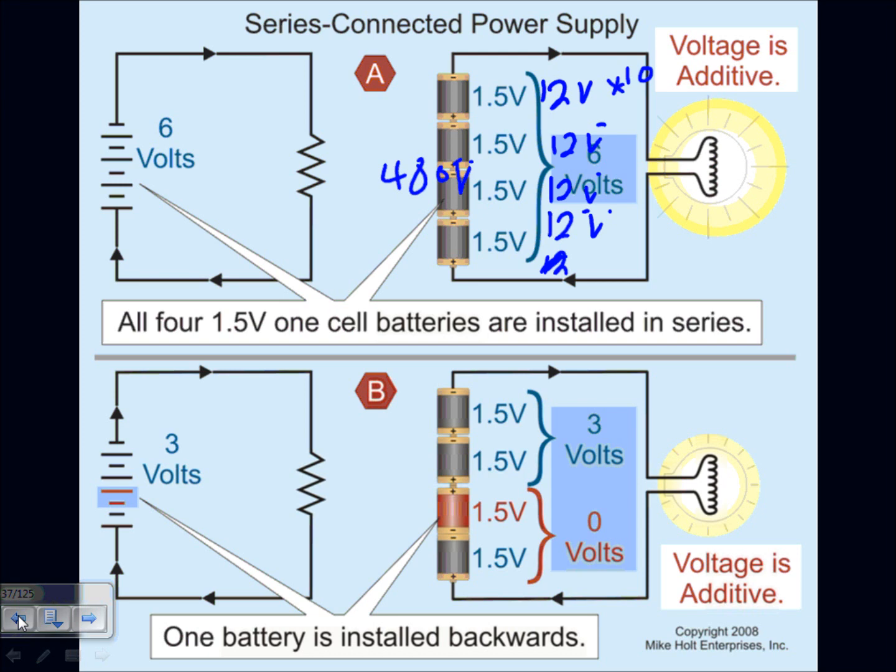Now, this string will give you 10 amps. Okay, so I got only 10 amps. I'm just throwing out this number. Now, suppose, Rob, you want another 10 amps at the same voltage. What would you do? Absolutely. You draw another line right here. Come over here, and you put all your batteries right in here. Tie it. So here you got another 10 amps, and so 10 amps coming out of here.